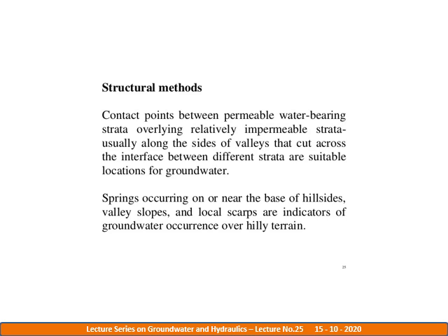Temperature is nearly constant, which is a great advantage if the water is used for heat exchange. Turbidity and color are generally negligible. Chemical composition is generally constant. Groundwater storage is always greater than surface water storage, so that groundwater supplies are not seriously affected by short duration drought. Biological contamination in groundwater is seldom noticed.